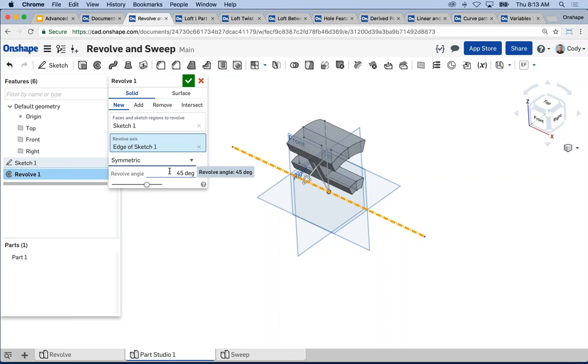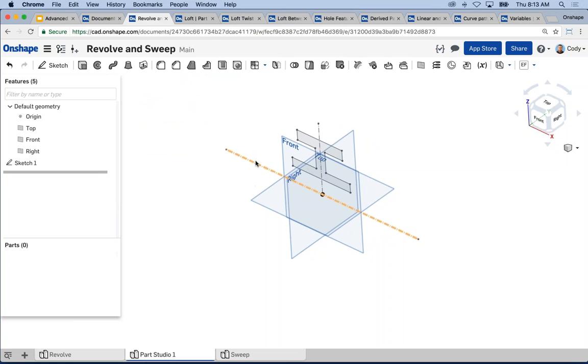All right, so that is the revolve command, a simple intro into the revolve command. The big tip that I would give you again is just the construction line to help define your revolve axis. It just makes dimensioning and defining the revolve axis very clean and easy. And also the ability to dimension to that construction line and then move past it to give you true diameter dimensions in a scenario like that. So oftentimes in revolve parts, you want to define with diameters, and using a construction line will help you do so. So that is revolve.